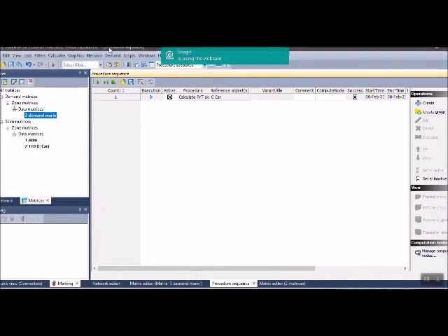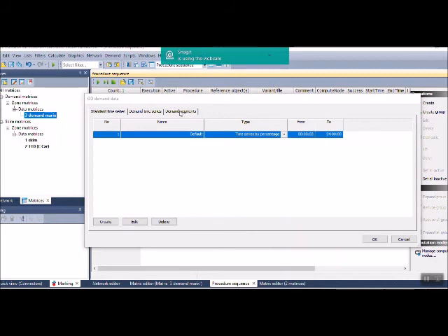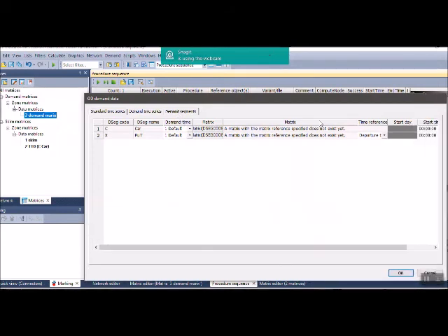we have to, before doing the run, go to demand and demand data, and in here we're going to select our matrix, select here demand segments, and from demand segment we are going to look for our newly created matrix in here.